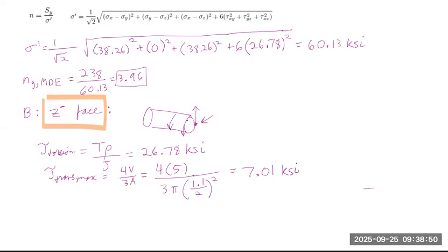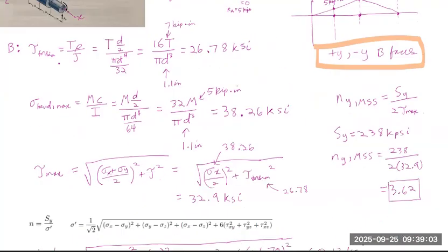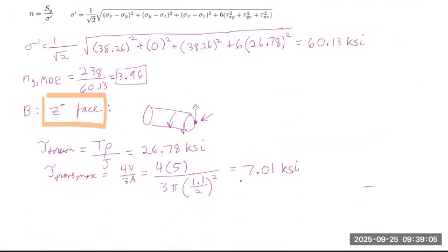And also, we have transverse shear stress due to the forces that are trying to bend this whole structure. We don't know the direction yet, but I'm just going to draw it like this, also pointing in the same direction along the y-axis. So we can just add these two components up since they are both pointing in the y direction.